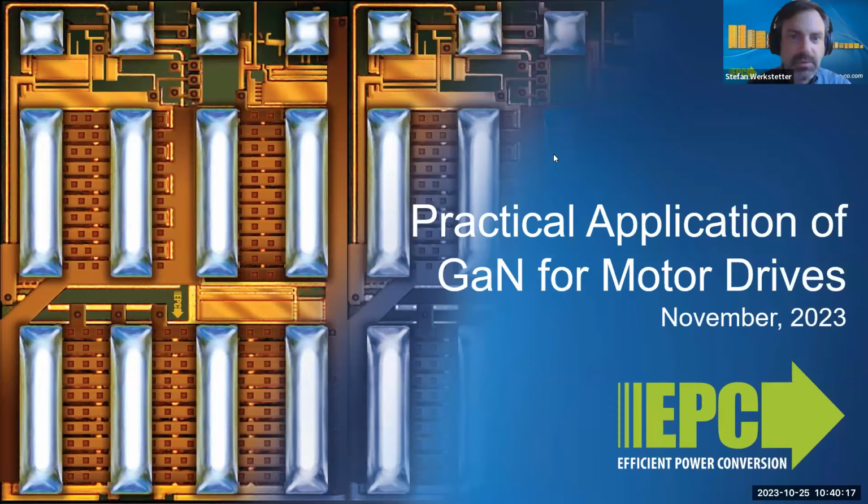Next question: is 1700 LFM needed for the 1/16th brick solution? That is a huge amount of airflow. Yes, it's a lot of airflow. You can still reduce the rate of the current and use more reasonable airflow on the solution, or add a heat sink on it. That's it.